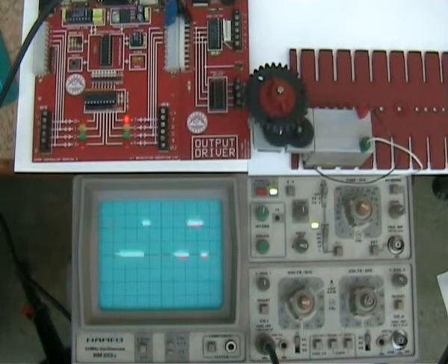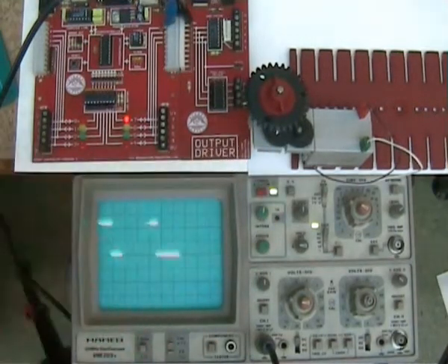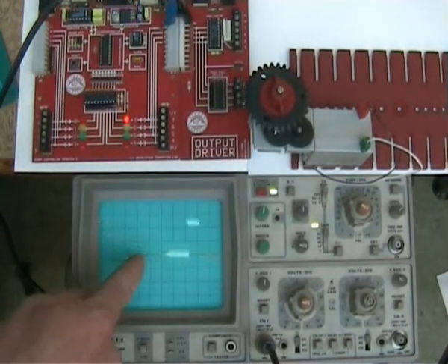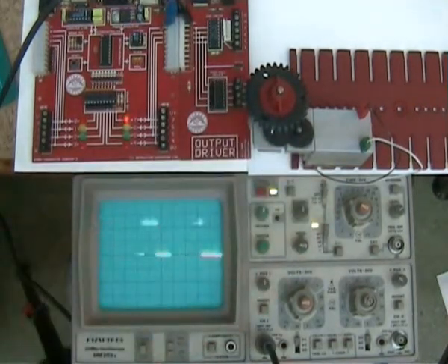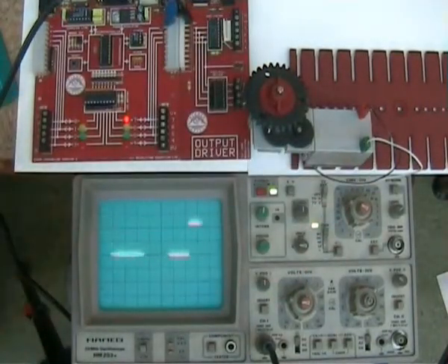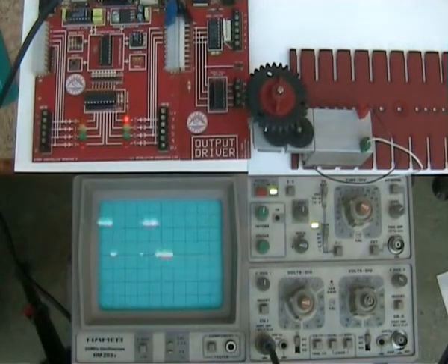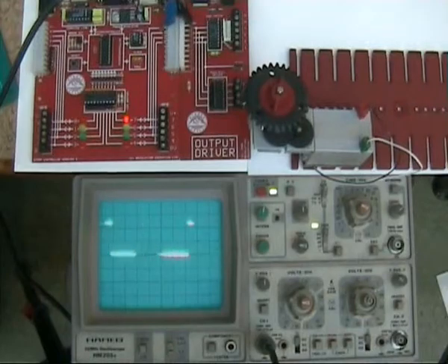The advantage of pulse width modulation is that you can get DC motors to run at very low speeds, and when you're switching on, you're getting the full torque out of the motor. The motor is a 9 volt motor, and the signal on the screen here is 0 and 9. So you're managing to get it to run with good torque at low speeds. Pulse width modulation, controlling the speed of a DC motor.